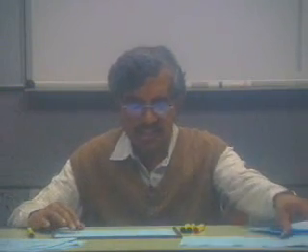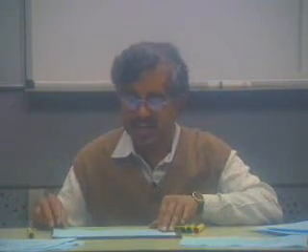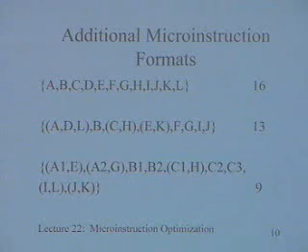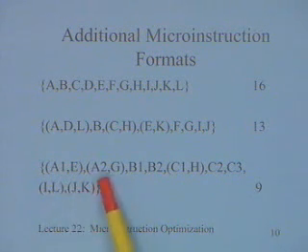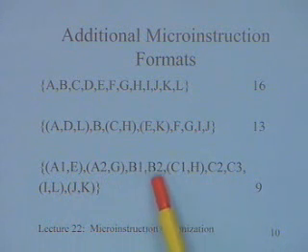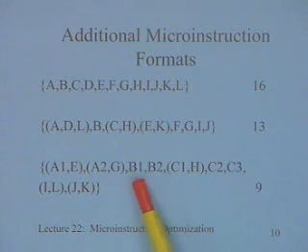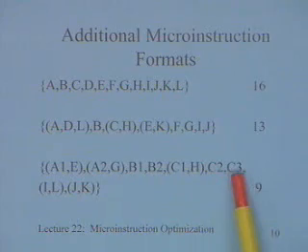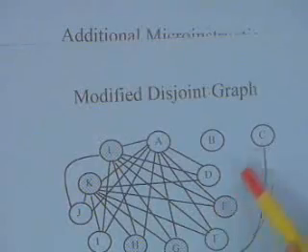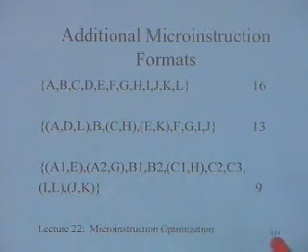in generating my partitioning, I am evaluating the cost of the cluster, and I can end up with a partition of this nature. So I replaced A with A1 and A2, so I can merge A1 with E, A2 with G. B1 and B2, of course they do not merge, because they are sequential instruction bits which are going to be there. C1 with H. C2, C3 again do not merge, because the branch address, C has only one edge with H, and H is only 1 bit, so you can only merge with one. C2, C3, IL, JK.